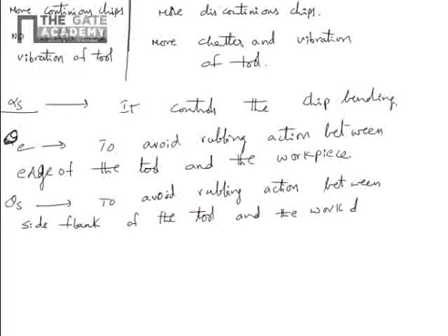So once rubbing action takes place, that means vibrations will start. Once vibration starts, the machining won't take place properly, so the surface finish will be rough. To avoid all this,